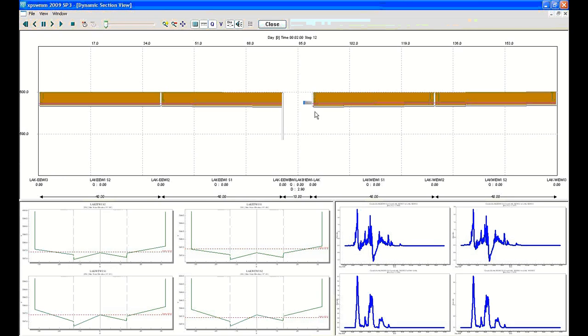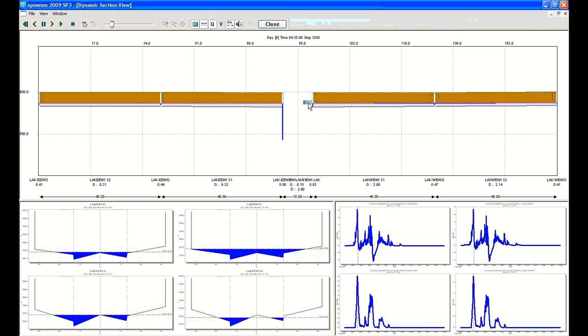So here's an example of a weir, and if I play this, you'll see the water actually come over the top of the weir. You can see that water flows both ways. You've got a negative flow here and a positive flow. So as the water comes up and goes over the berms, the water gets in. Whenever you see a deep area like this, what's going on there is that's a catch basin, and the water is going from the catch basin to the combined sewer. So here you can see right now that it is overtopping the berm, and blue is over the top of the little berm there.